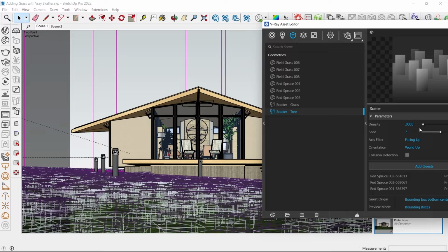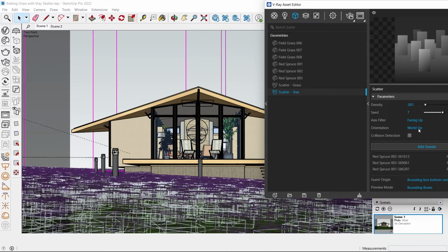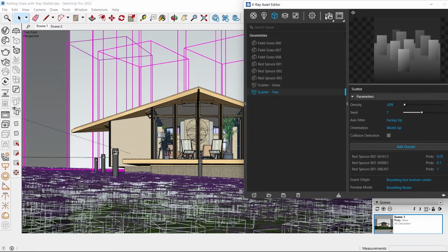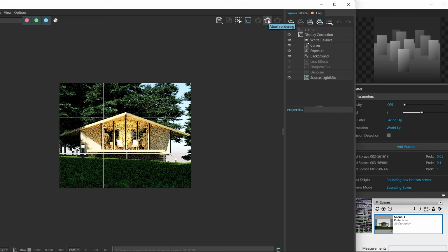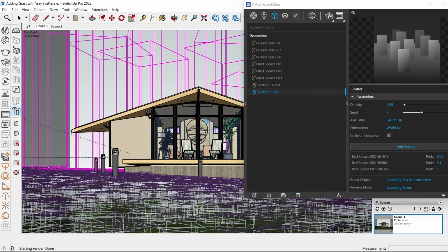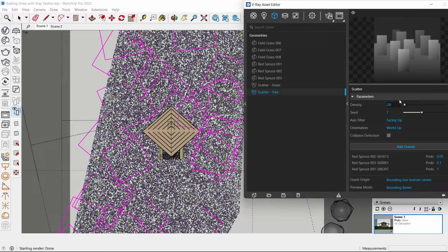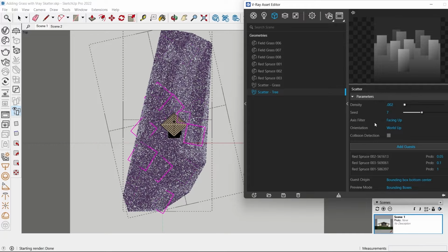Okay, now there's hardly any trees in the scene, so maybe just bring it closer. Alright, 0.009. Let's run an interactive render. Okay, it seems to be the same. So let's stop the render. We'll go to the top view for better understanding of the trees. Let's bring this down to 0.005. Alright, so that's definitely reduced the number of trees. Alright, 0.002. Let's see how this looks.